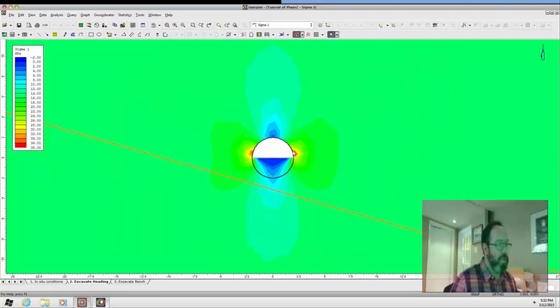So we can see we've got some high stresses developing over here on the spring line, which is very consistent with a high vertical stress, up to 38 MPa or so. Very high. That's about twice the in situ stress level that we entered, and that seems reasonable. And they're very low in the roof of the tunnel, in fact possibly even tensile, which is also consistent with this kind of stress regime.